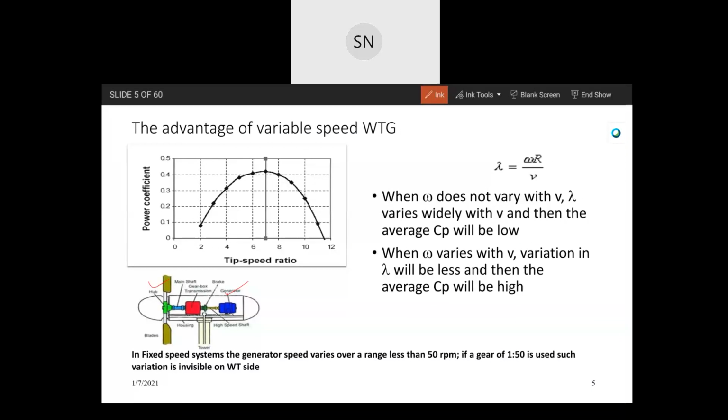I'll tell you. Now the speed is decided as a requirement to transfer the power. A machine means a power converter. The wind turbine is one machine, and the electrical generator is another machine. When these two machines are interconnected, even though the coupling is through a gear, any change in the speed on either shaft will have a proportional change. So you can consider that the speed change will be together. The turbine and the generator cannot have different speeds.